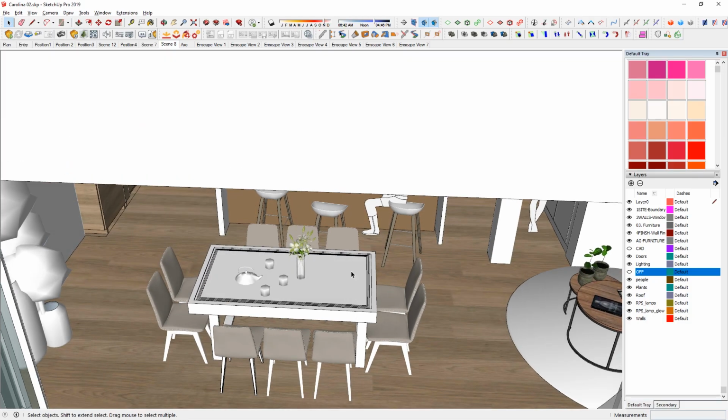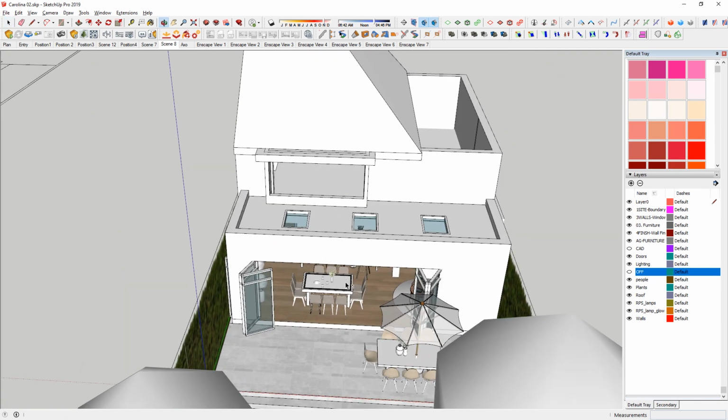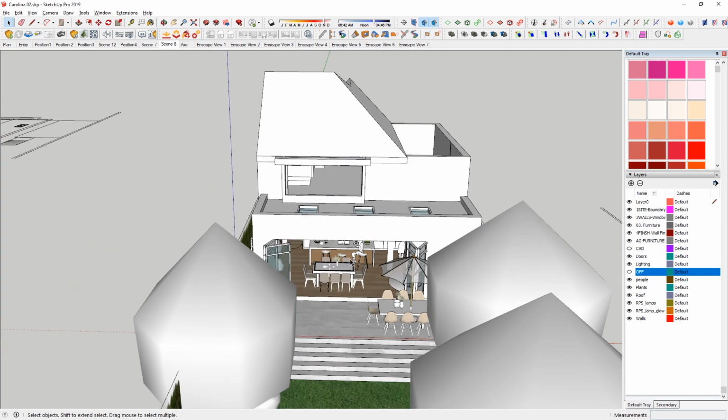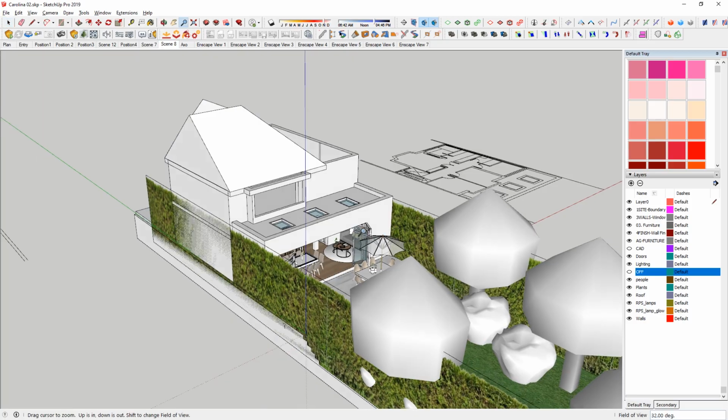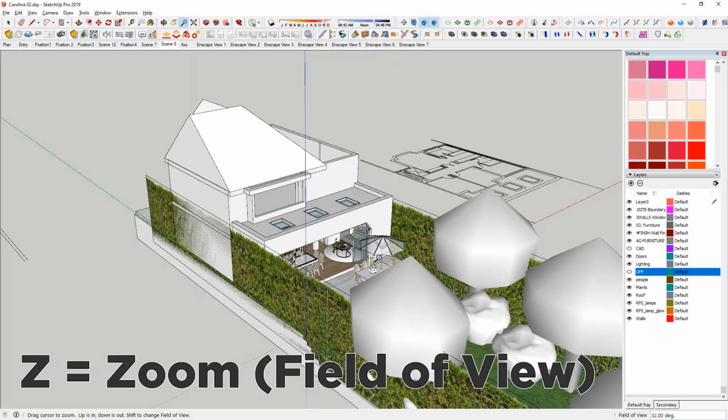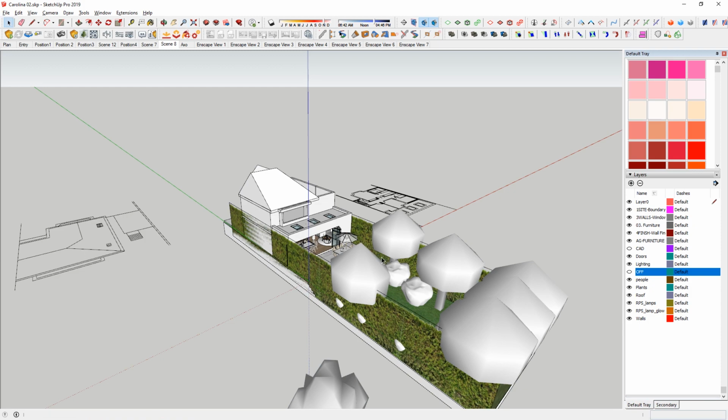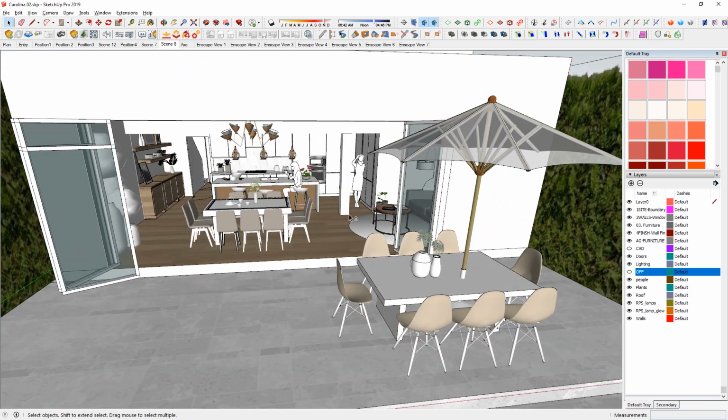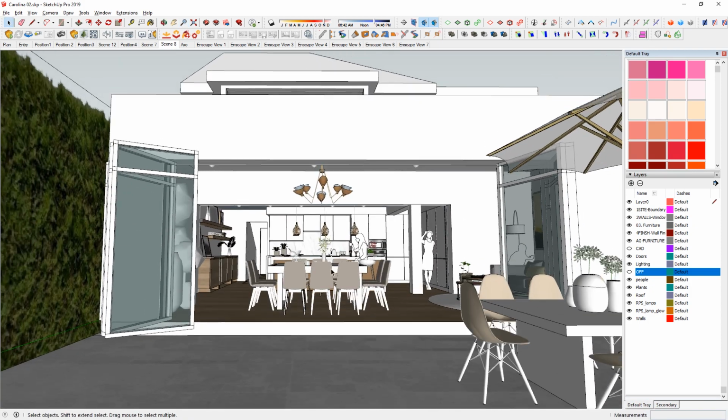Okay, that's fine. Let me just turn off hidden geometry so that my computer is not struggling as much. I'm gonna create one scene so I can just look at everything clearly. Especially when I'm working on an interior model, I'm gonna set things up at a 60-degree wide angle. So I'm gonna hit Z once and 60 DEG, enter. And things are gonna be much wider so that I can swim a lot easier inside of my model.